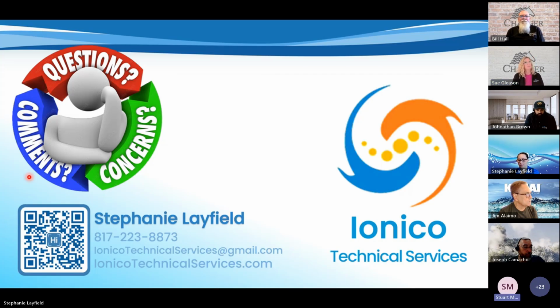Play when we do an electronic profile. So one thing that we can do, and it's on the Charger website, is that water test that we offer. I think it's about $275. If you do the most advanced one, that has everything that you need to do an electronic profile of an RO. And if you take that up with your customer, you do that test, then we can determine how much you're going to produce, what the pre-treatment's going to be, what the most efficient way of doing things is, and provide you a great solution to your customer. It's pretty accurate if you follow the rules.